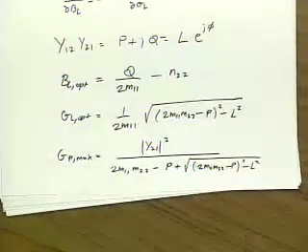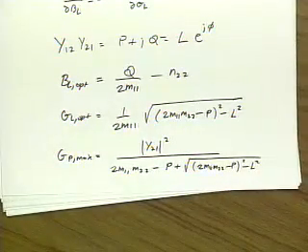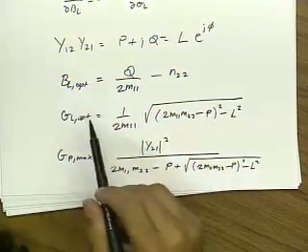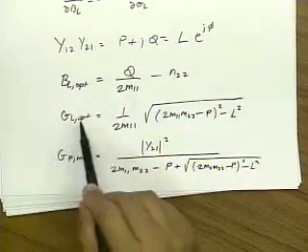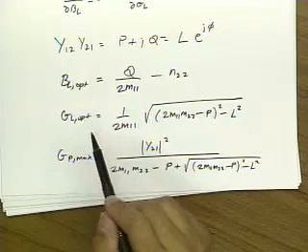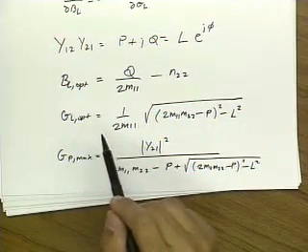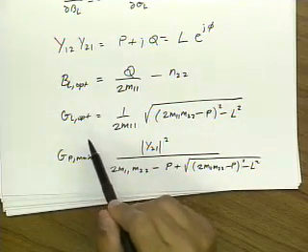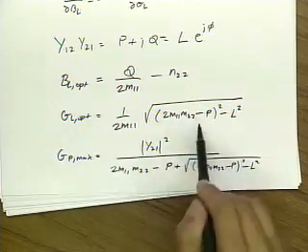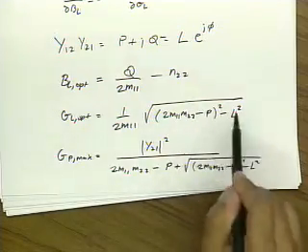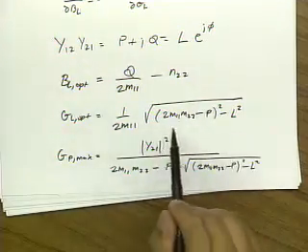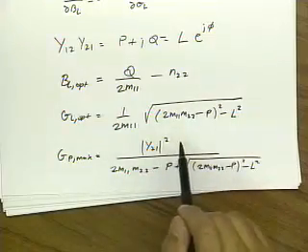Now don't copy this down. The important thing is to notice that this is a conductance, so it has to be positive. Negative conductance doesn't exist physically, at least not as a passive termination. So for this to exist, this term has to be bigger than this term. And that's exactly the condition that we talked about earlier under which a solution exists.